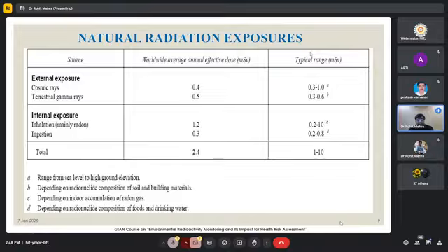I will be presenting those results to you also, where we will be dealing with how this mixing of fly ash in the OPC cement has enhanced the level of radioactivity. That is the con for the use of fly ash. We were discussing the pros only as a civil engineering aspect, but there are cons, and I will show you some results which are very interesting and informative, like how the different concentrations have enhanced the level of radium, thorium and potassium.